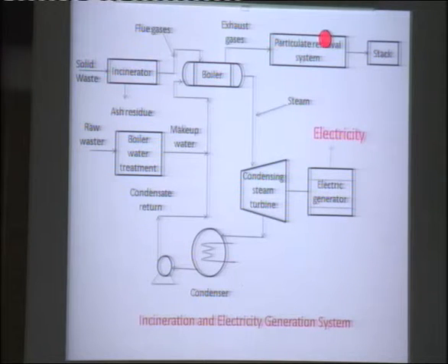Benefits derived from the incinerator: you can get steam, which can be utilized for food processing, drying purposes, textile, leather, pulp and paper, or electricity can be sent to the local grid. But the concern is the emission of gaseous and particulate pollutants, which are to be cleaned properly, and leaching into contaminated soil and groundwater.